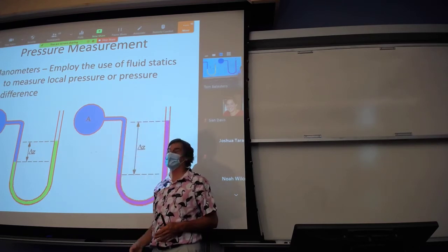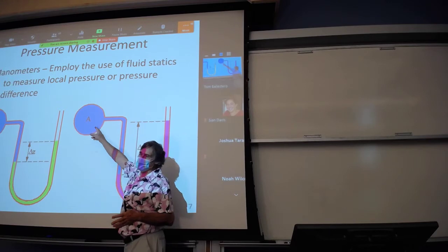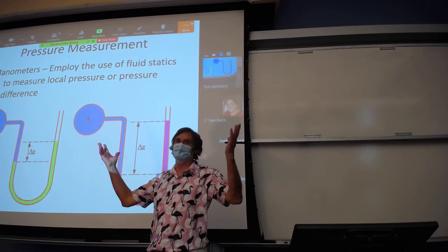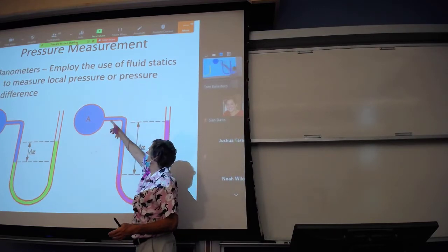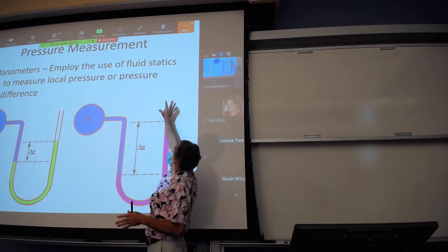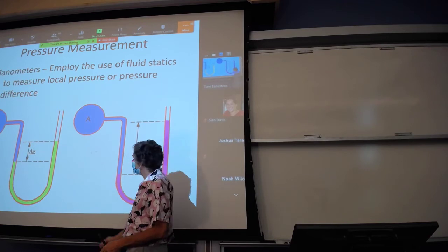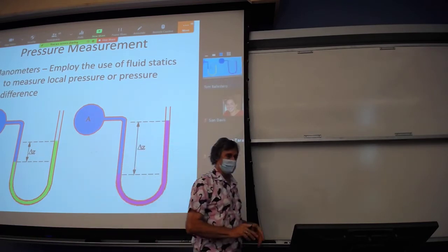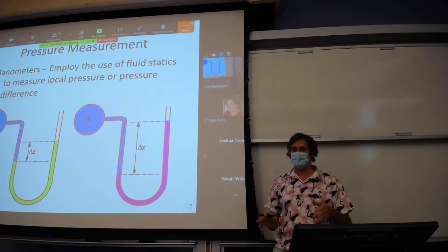That's what you're going to have in the fluids layer when we look at energy losses. So I'll call that a pressure vessel, but it could be almost anything. It could be a tank, could be a pipe, could be a lot of things. And basically, if there's two locations on either end, we call it a differential manometer. So say you have another pressure vessel here, pressure vessel there. If it's just open to the atmosphere, that's just a manometer. So again, these are all very common methods of measuring fluid pressures.